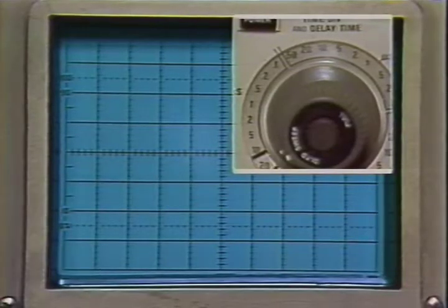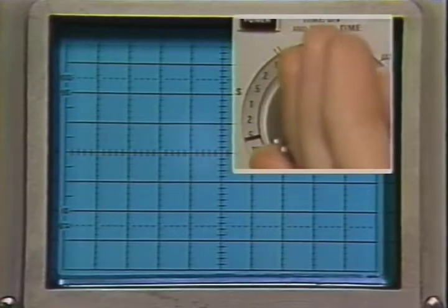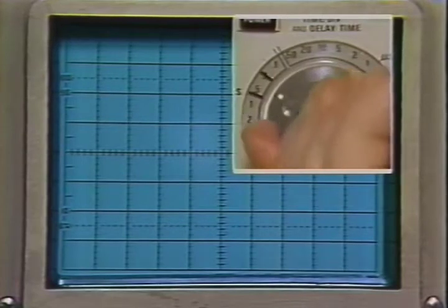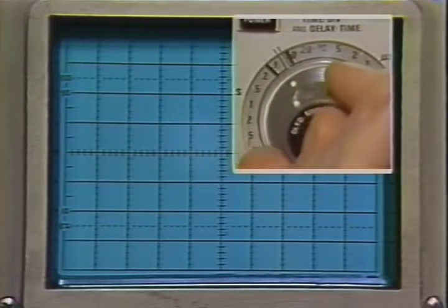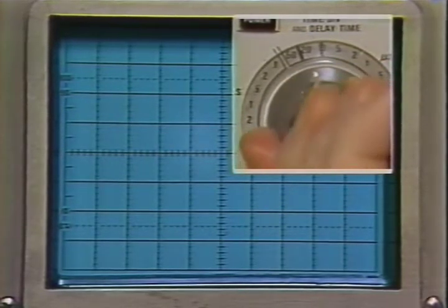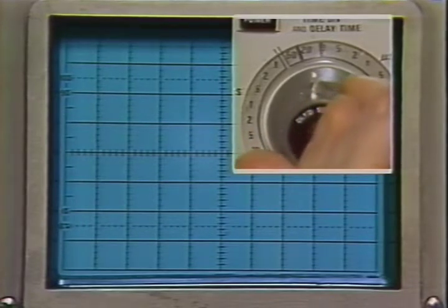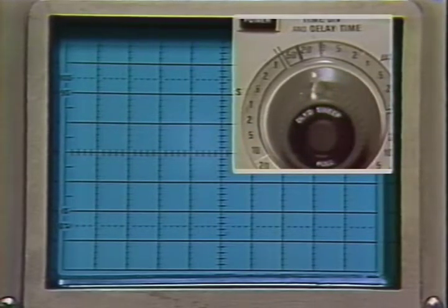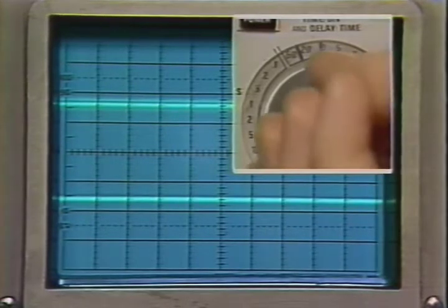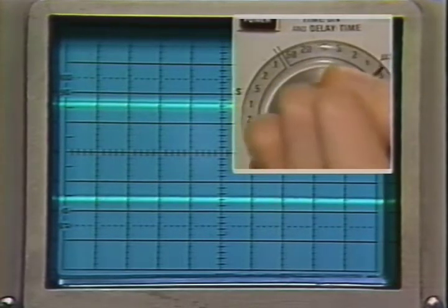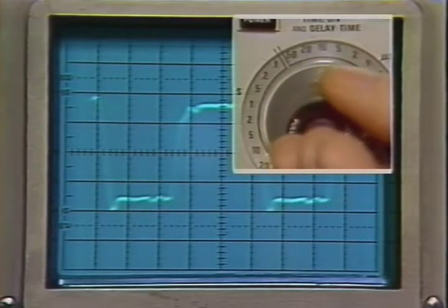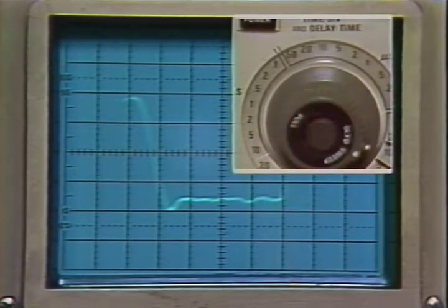As the scanning beam in a normal oscilloscope goes faster and faster, there are less and less electrons per sweep to excite the phosphor. At very high sweep speeds, there are too few to make the phosphor glow visibly with a single sweep. If there are several thousand sweeps per second, they supply enough electrons. It's the number of electrons per second that makes the phosphor glow.